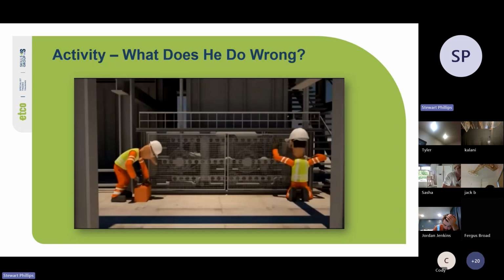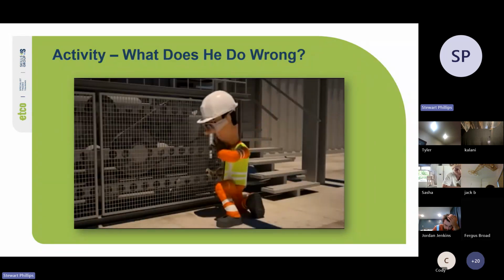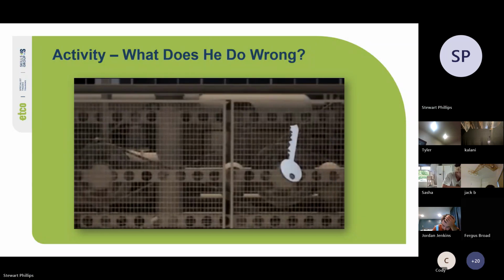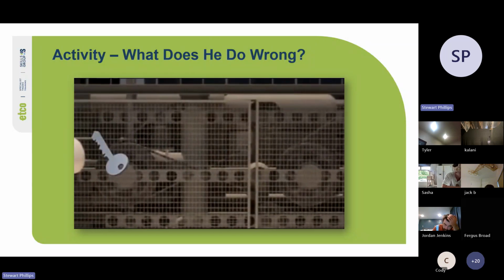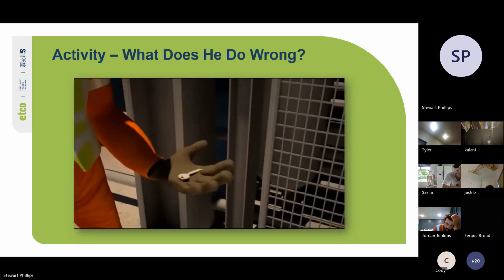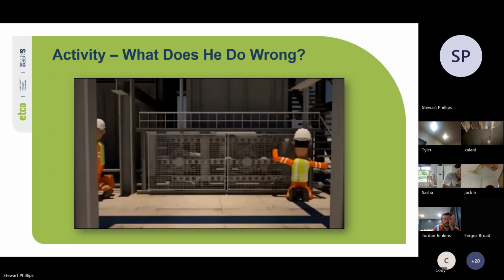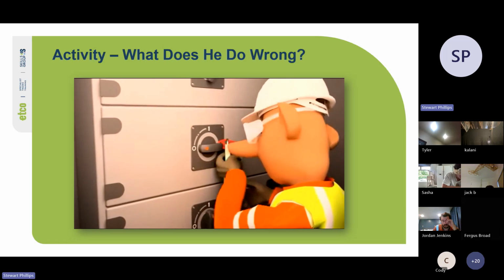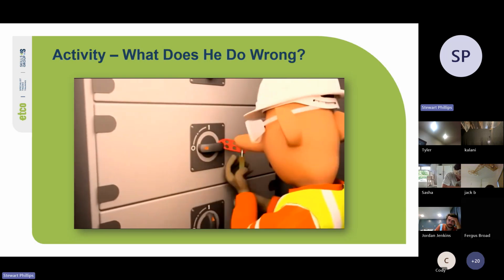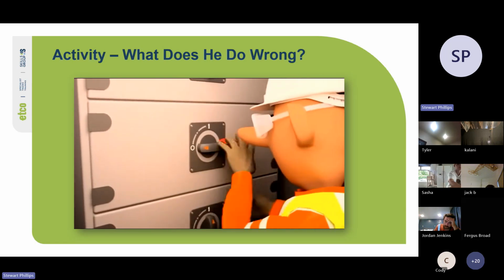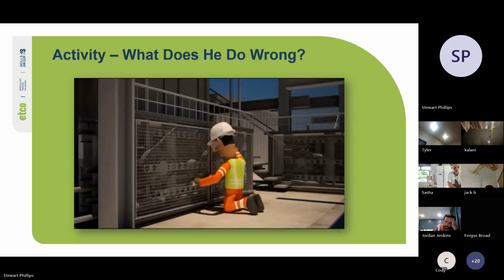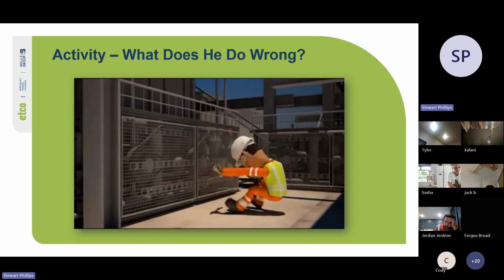Yeah, so if you're the person who puts the tag and the lockout on, you should always keep the key with you. Never just give it to someone else. It's your responsibility to make sure you isolate and then release that equipment properly. Don't just give it to your mate because it's easier, especially if you're still working on the machine.